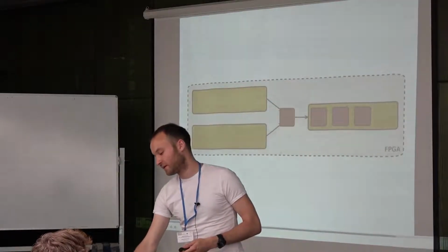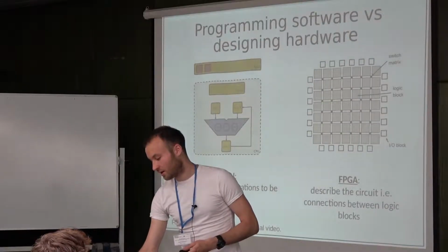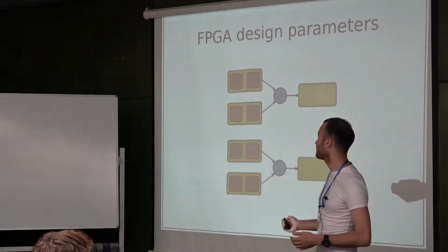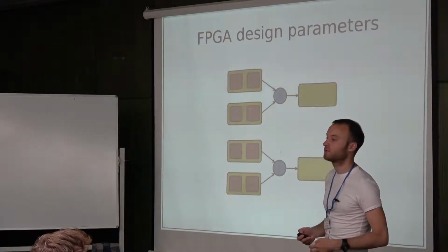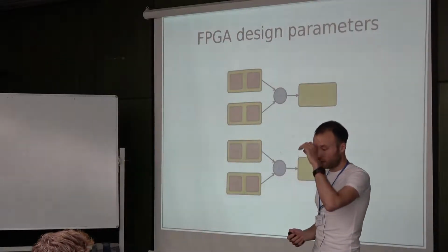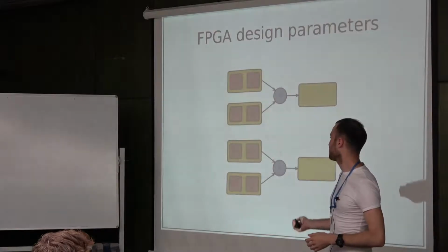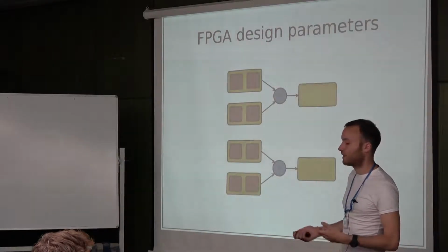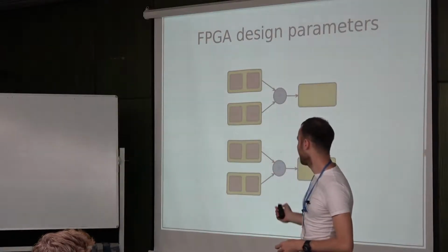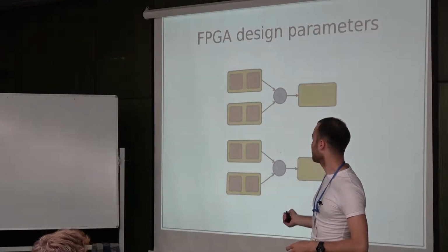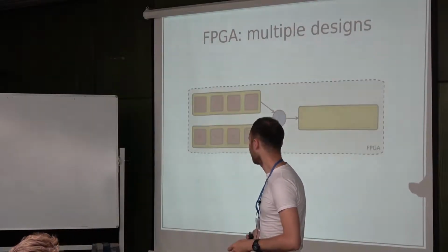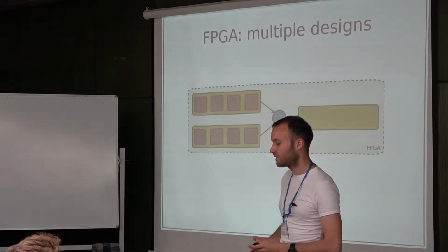In addition to pipelining, we can also partition memory blocks. So we are not restricted by memory. So we can have multiple small memory blocks or one large memory. So it's up to us. So we partition memory, and then we replicate computational units and do computations faster. In this case, we don't have any dependencies, and it is likely that we will end up with a design which is twice faster than pipeline design without any parallelization.